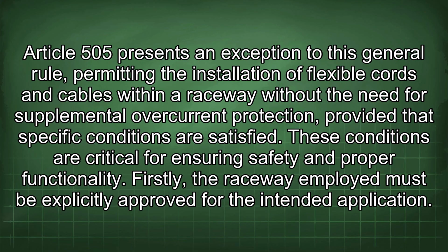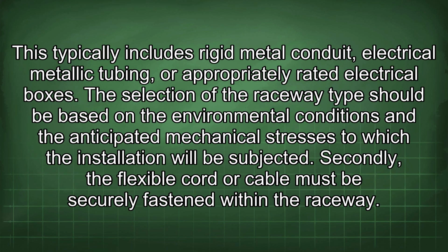Firstly, the raceway employed must be explicitly approved for the intended application. This typically includes rigid metal conduit, electrical metallic tubing, or appropriately rated electrical boxes. The selection of the raceway type should be based on the environmental conditions and the anticipated mechanical stresses to which the installation will be subjected.